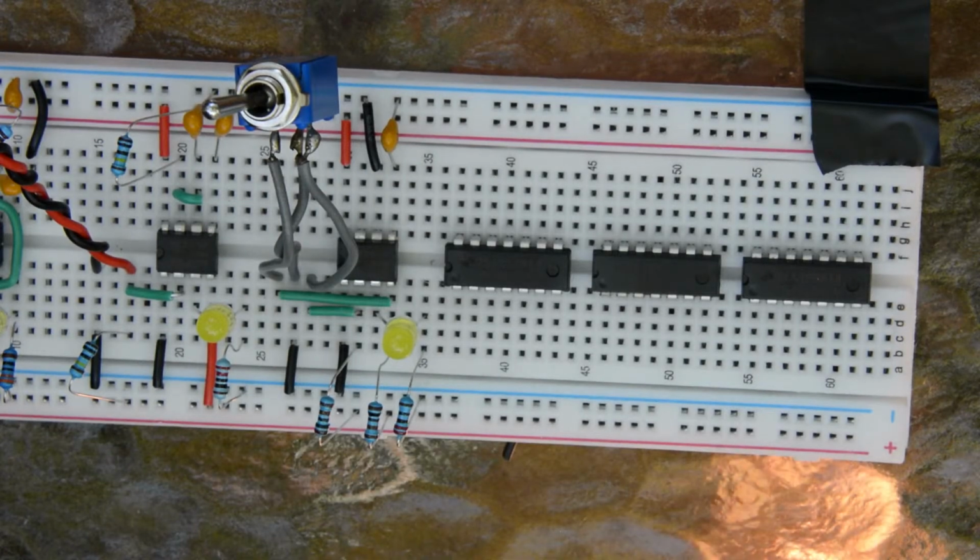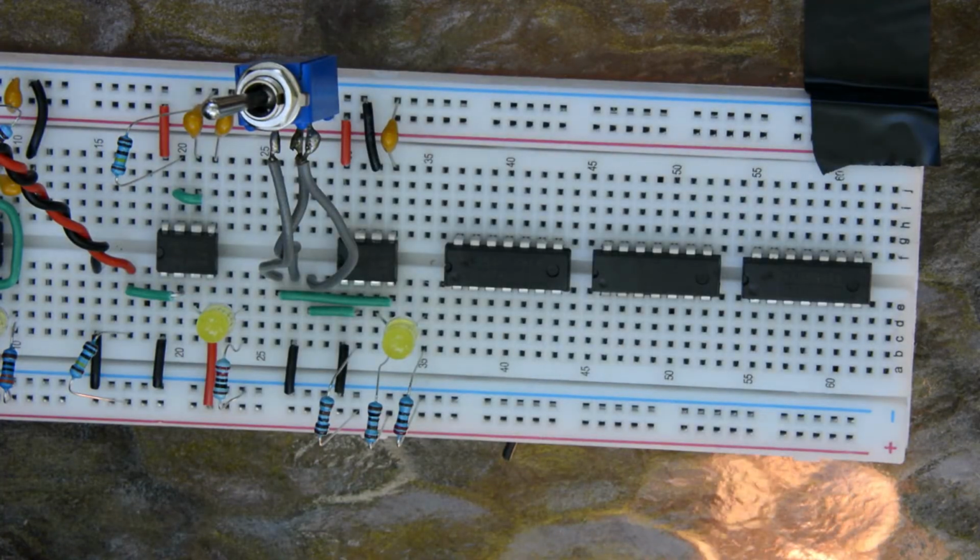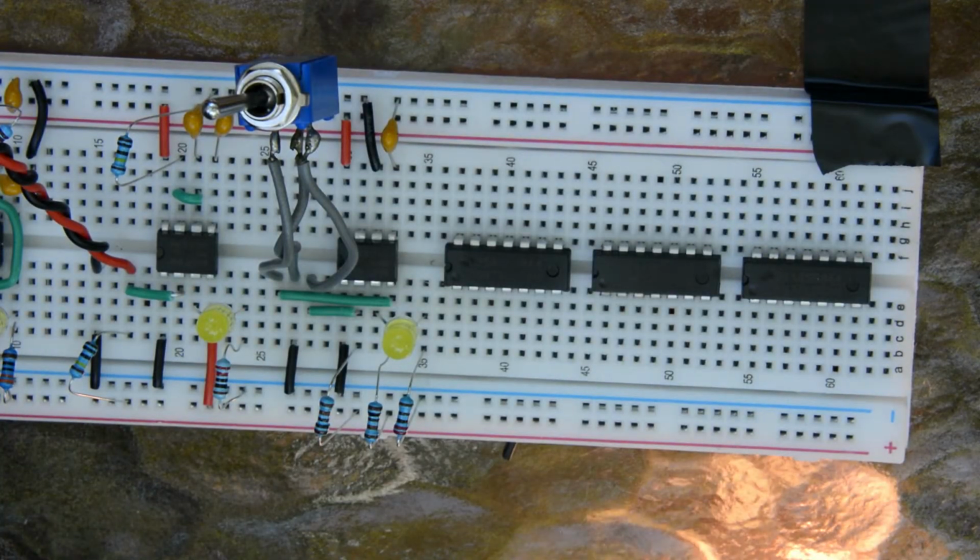For LS32, all hooked up here. And you can see I hooked up the power pin to pin 14 and the ground to pin 7 for all of these. And that's how they all are. If we look at the data sheet for 74LS04, for example, you can see power pin 14, ground is pin 7, and it's got the 6 inverters on there. We're only using 2 of them.